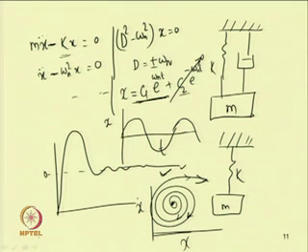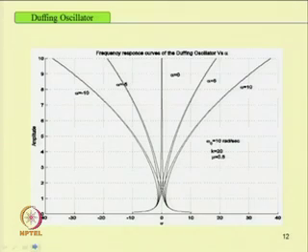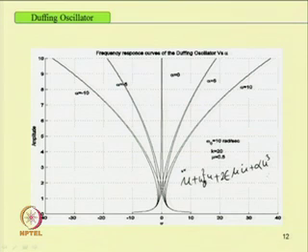So, for studying the stability of the systems, there are several methods. Let us first see different responses of the system, for example, in case of the Duffing equation with damping. Let us consider the Duffing equation with damping, that is, if you take the equation in this form, u double dot plus omega n square (omega 0 square) u plus 2 mu (or 2 epsilon mu) u dot plus alpha u cube equal to 0.